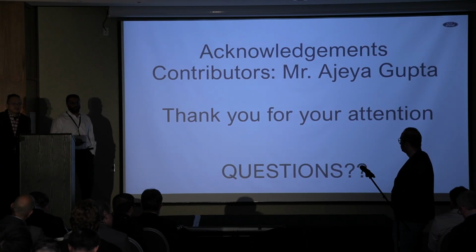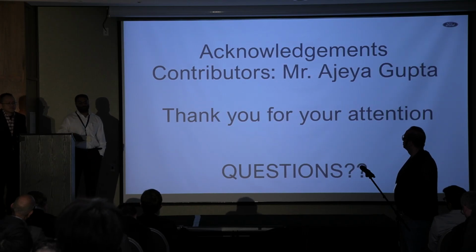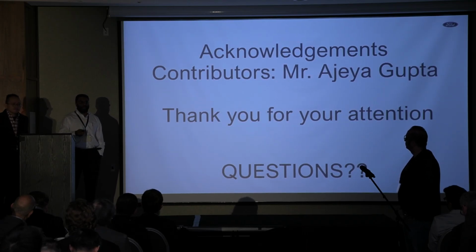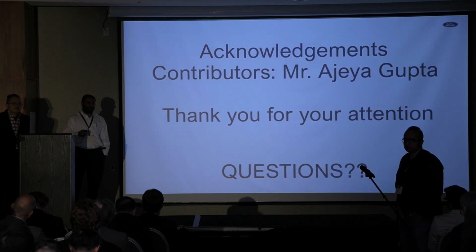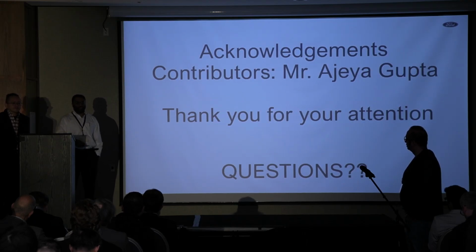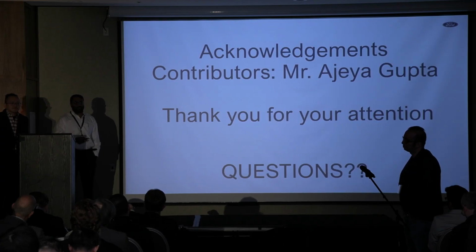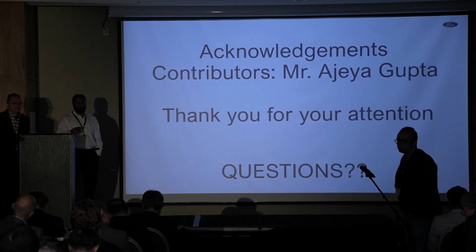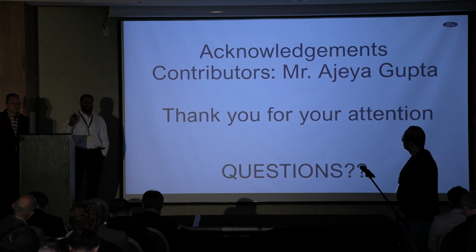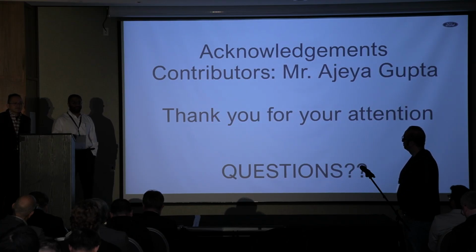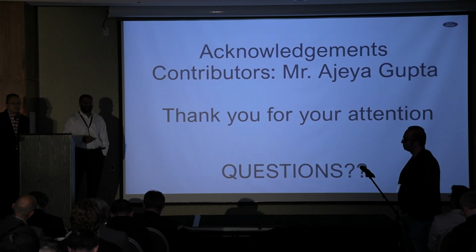Yeah, definitely, good question. As an OEM at Ford, we do have a qualified part list. So we evaluate every 5 vendors, at least what we have in the market, at least for the 10Base-T1. We do that for all parts. We go through EMC testing. We require the vendors to provide us, and as they pass the requirements, we will add it to our supplier approved list. That is also given to the tier 1 suppliers so that they can pick any of these from our approved part list. But that is specific to some internal testing and the EMC testing that the 5 vendors are required to do to get onto our approved part list. Okay, thanks, got it.